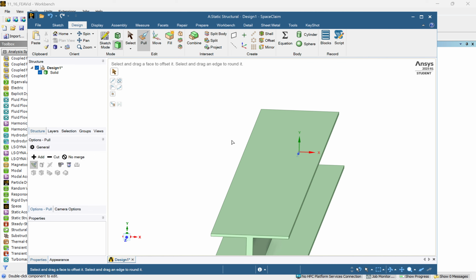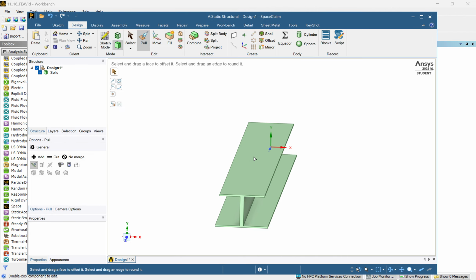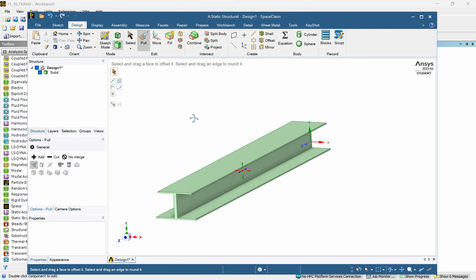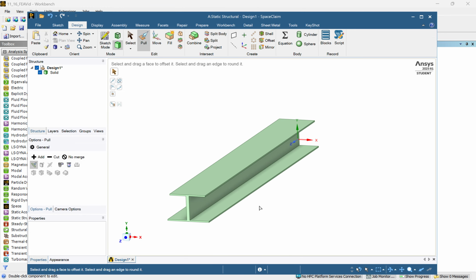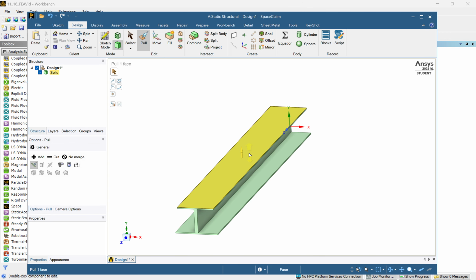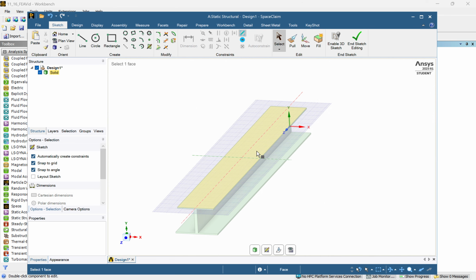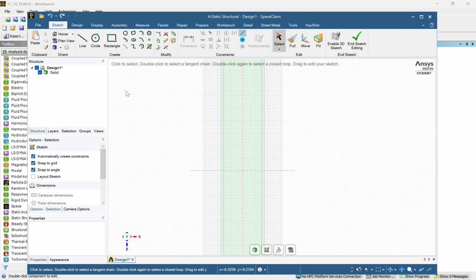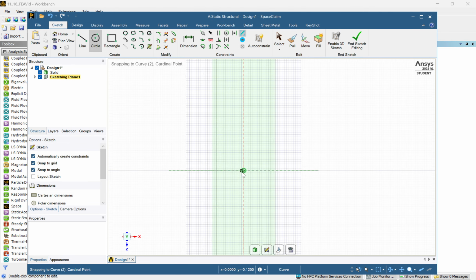The last thing we need to add here is sketches for where the loads are going to be applied. So we do a 3-point beam test or bend test. So we're going to need fixed supports down here, and the actual Instron that we use in the competition pushes down on the beam in the center. So we're going to do a couple more sketches here just to get that done. So let's align it here. Our contact surface for the Instron is going to be just a small circle. We'll do 0.25 inches in diameter.